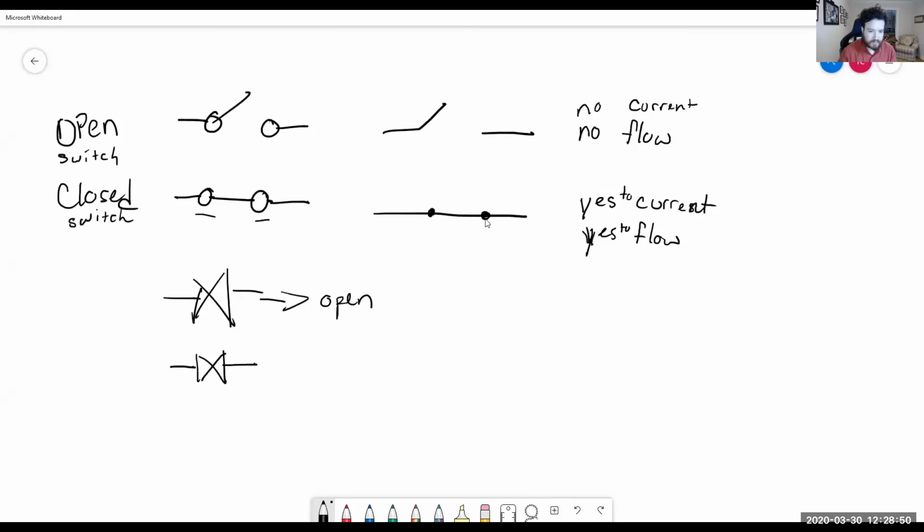So, whereas if we have a closed switch, then we're not going to have flow. All right. They're opposite of each other. The electric and the mechanical version are very opposite of each other with this terminology. So an open valve, it's open. It has flow going through it. But an open switch, it's open. There's space in between it. It's an open air.